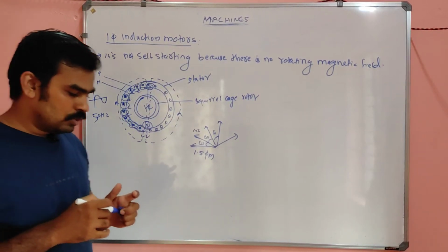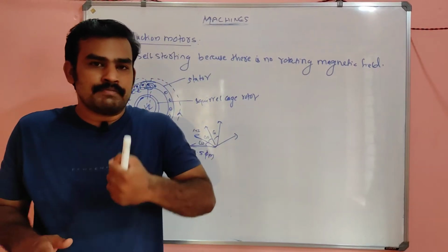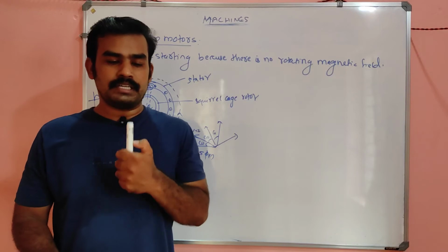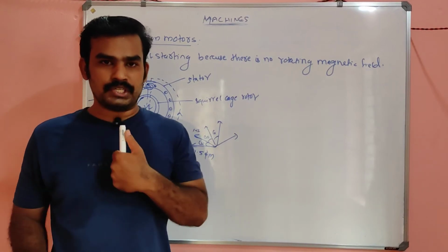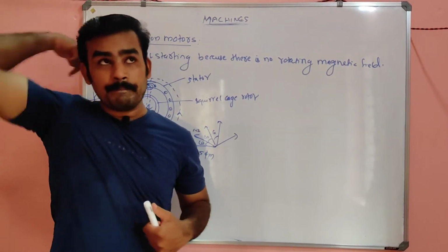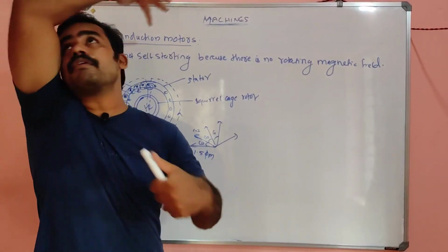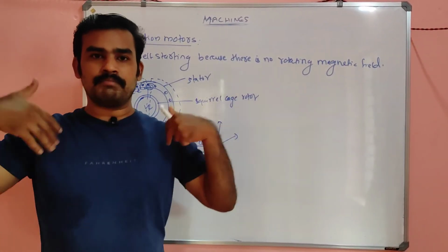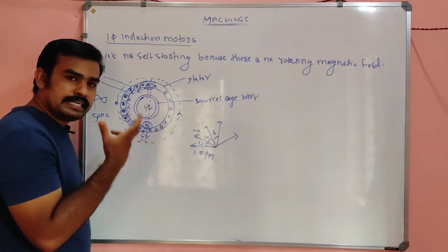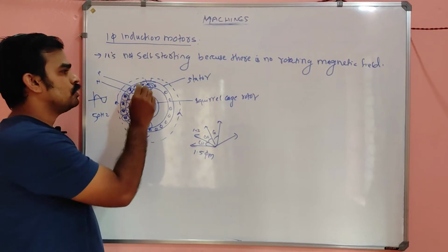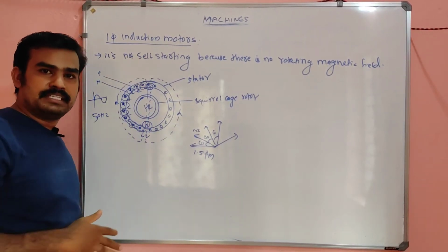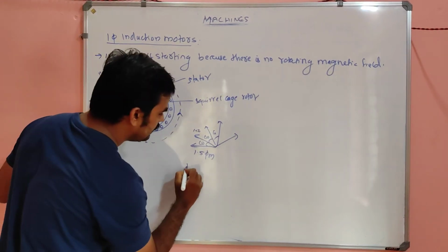My dear, in a 3-phase induction motor, what was the reason for the rotor to start rotating? The rotor is stationary. Suppose I am the rotor, stationary, and someone is rotating around me with some synchronous speed. So I am looking at that, and that was the reason the flux cuts me and I start rotating. But here, the rotor itself has some inertia, so this south, this north, this south is continuously varying and fluctuating. That is called the pulsating